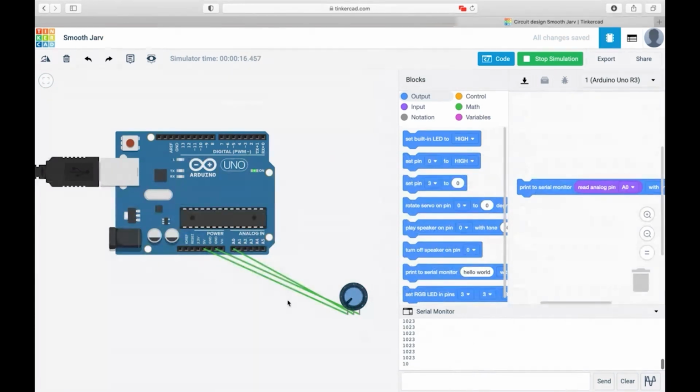It is because this analog input is converted to digital form with an A to D converter. In this Arduino board there are inbuilt 10-bit A to D converters, with the help of which anything analog given over here is converted to digital.